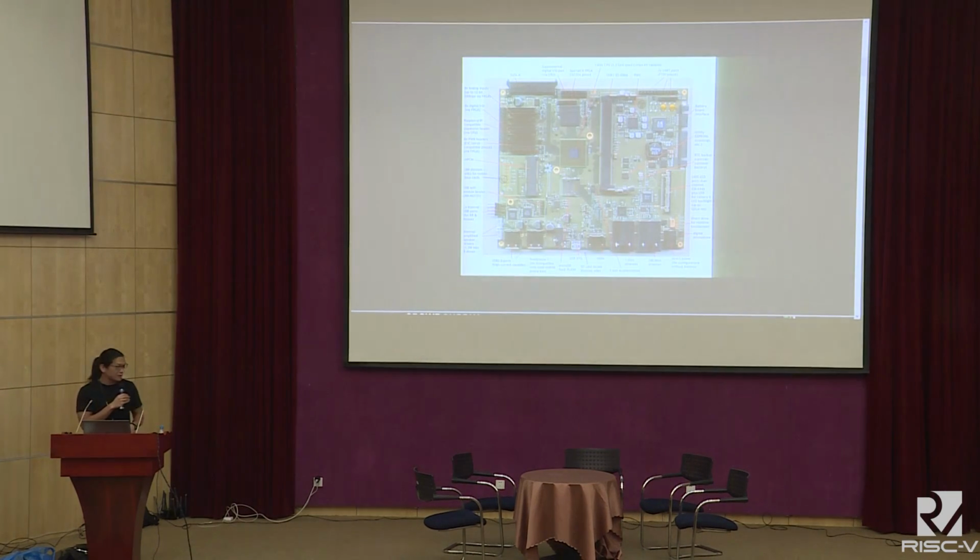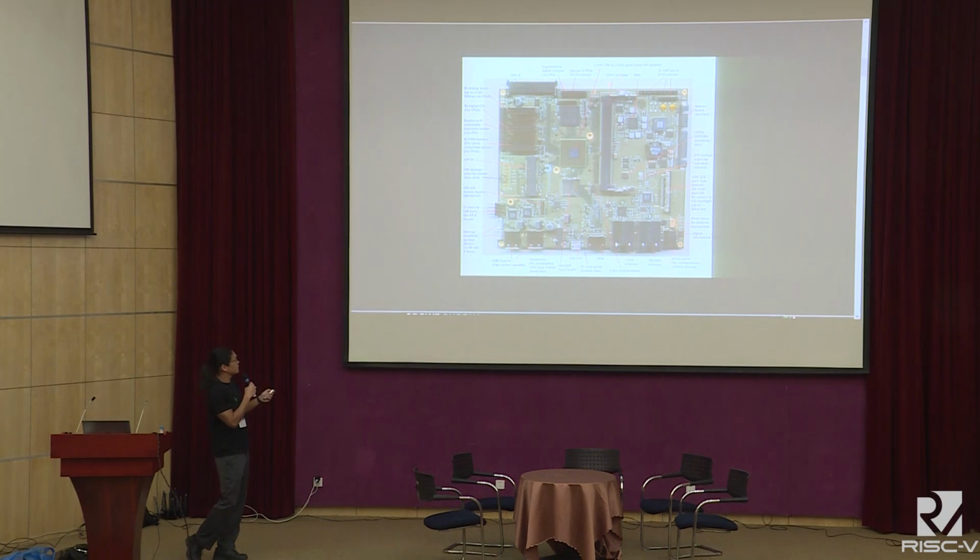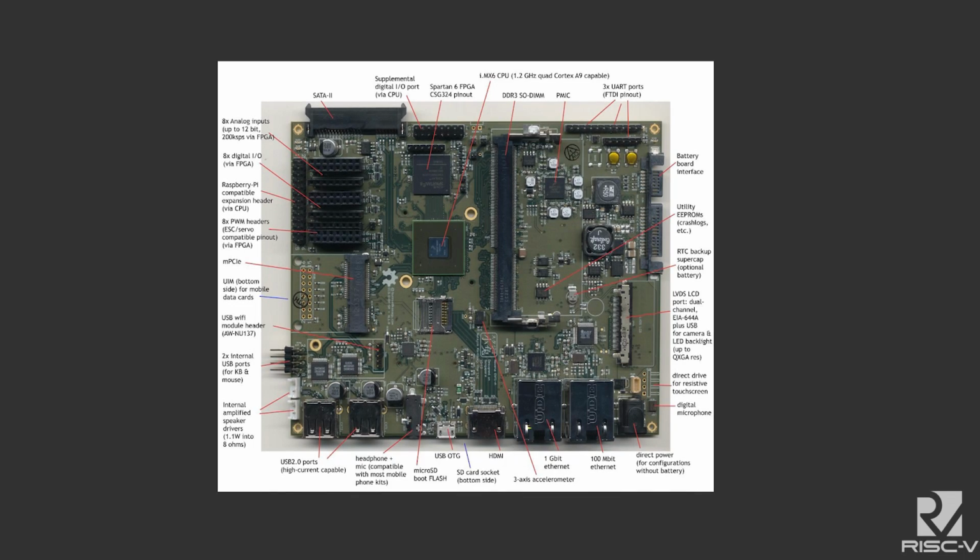And so we ended up designing this motherboard here, which is based on an IMX6 CPU SoC. It's a Cortex-A9, and it has weird features like 2 Ethernet ports built in. It has an FPGA on board, and the video interface is actually a card, so you can talk to multiple different LCD panels, and a bunch of other weird things. But if you were to build a laptop just for yourself, you would put those features in there.